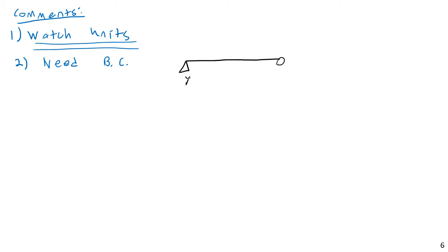Instead, you know that the deflection is equal to 0 here, and the deflection is equal to 0 here. So what you need to do is work all the way through the deflection, basically keeping a C3 and a C4. Then you substitute in those at the end when you have the final deflection, and you solve algebraically for C3 and C4.